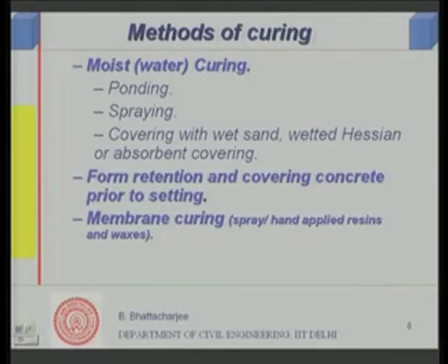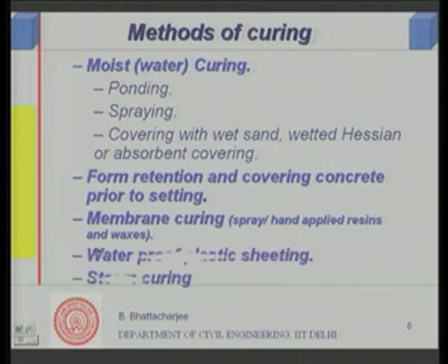If possible, there is nothing better than moist curing. Okay. So that is it. Then you can have plastic sheet covering, polythene covers. You can use polythene covers or something of that kind in order to prevent loss of water. Where you have no water, what to do? You use either the membrane curing compounds or waterproof plastic sheeting. So that is the other way of doing it.